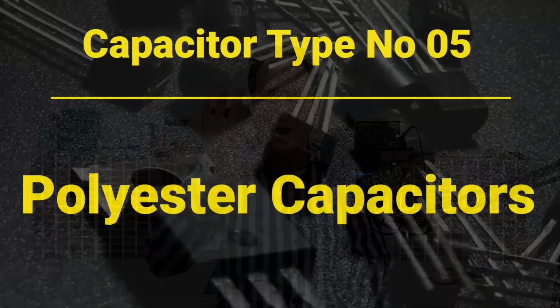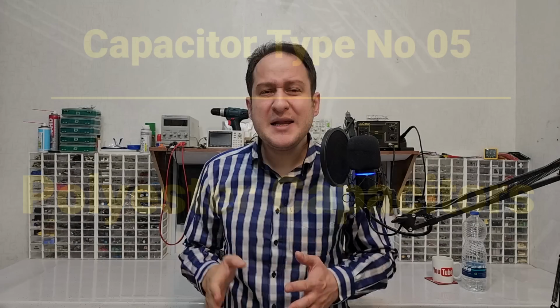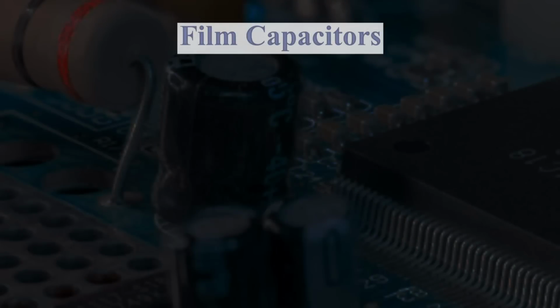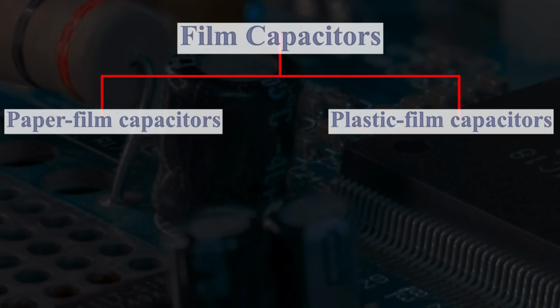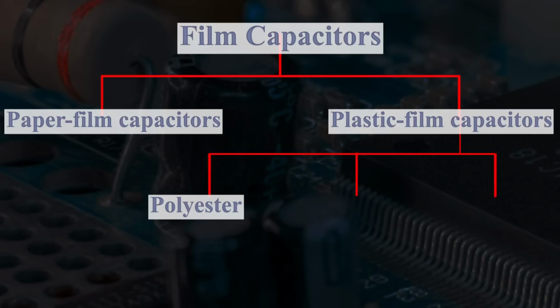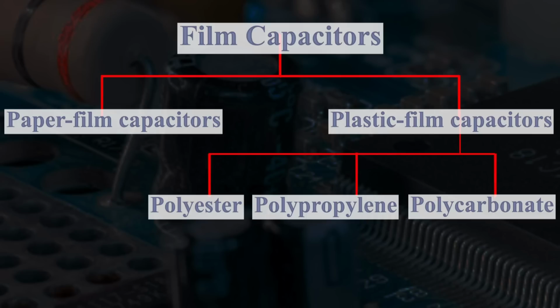Capacitor type number 5, polyester capacitors. Polyester capacitors are very stable, especially to temperature changes. Polyester capacitors are a kind of film capacitors. Film capacitors are divided into two main subcategories: paper film capacitors and plastic film capacitors. Plastic film capacitors are also divided into several groups according to the plastic material used in it as dielectric: polyester, polypropylene, polycarbonate, etc. All of these plastic film capacitors have similar features with a slight difference.